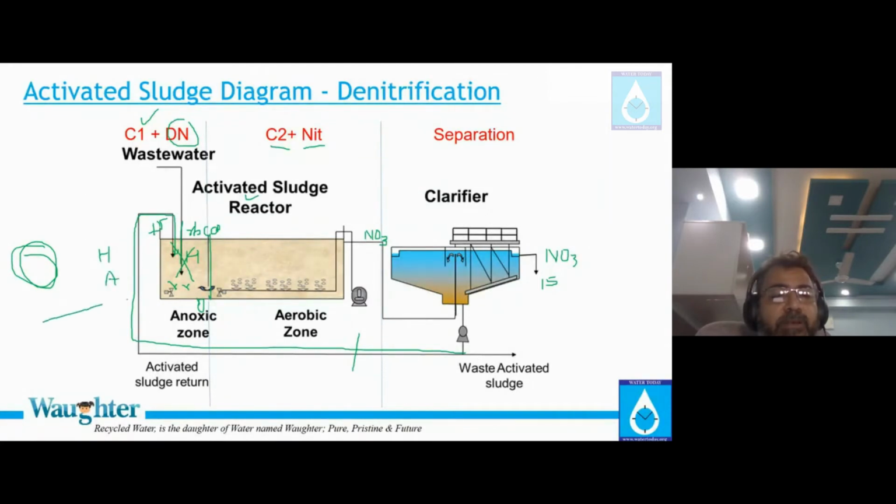Somebody was asking me yesterday how to design the anoxic tank retention time and sizing. Let me tell you very frankly, even today at my age, it becomes difficult at times for me to design an anoxic system. One thing I know very well, I can design for heterotrophs, but I really do not know how much time my autotrophs will survive before dying. Microbiologists also cannot predict their death rate in that much time because the equations are complicated. I actually do not know, to be very honest.